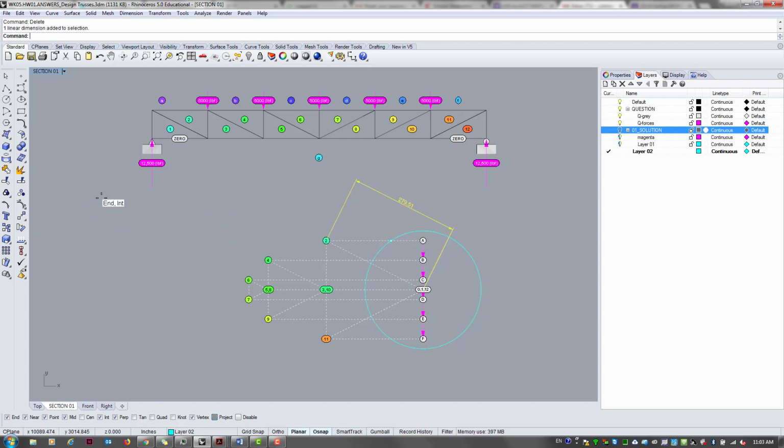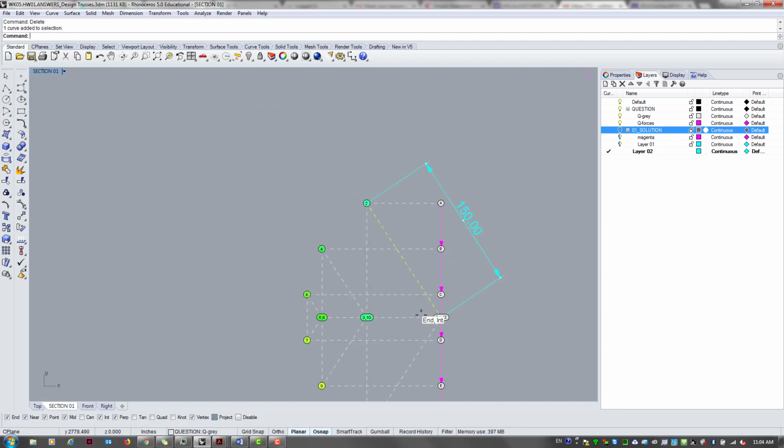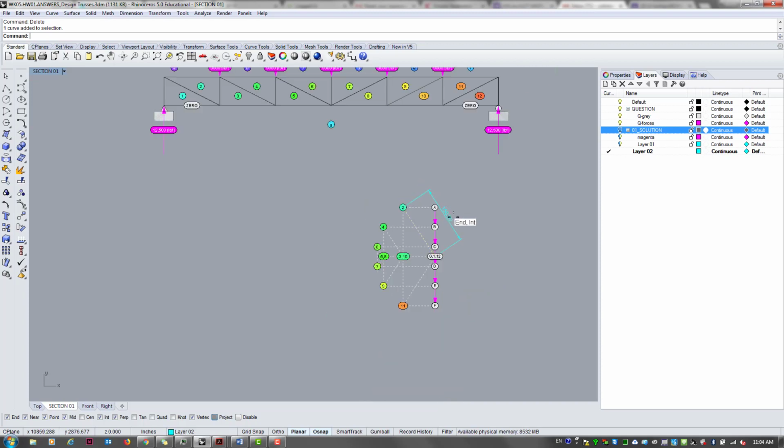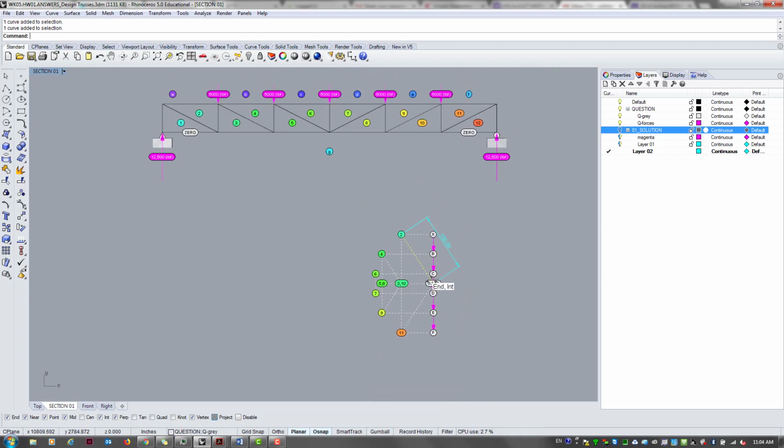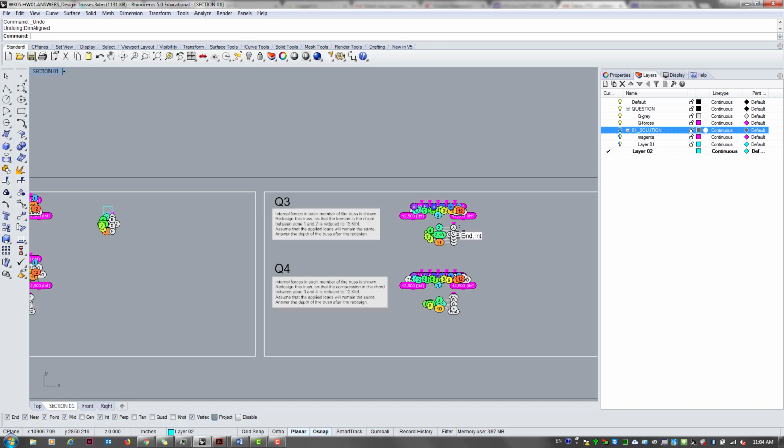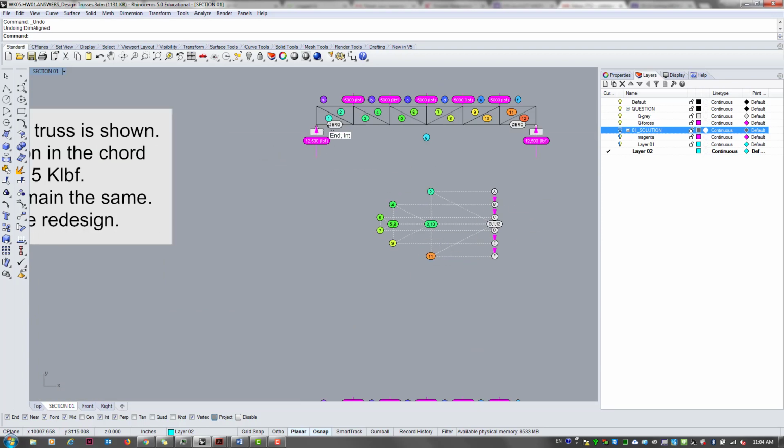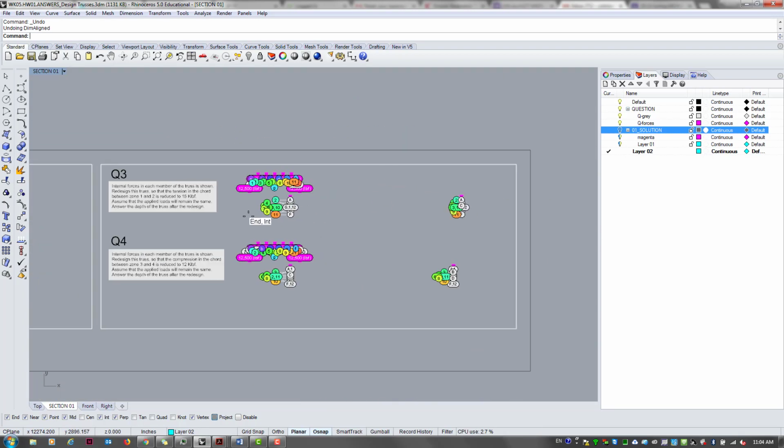And so I'm gonna turn the edit point on for this dimension. I'm gonna grab this whole thing and then scale 1D and grab the 2 and make sure that it snaps to that point. That way the resulting 1, 2 ends up being 150 inches. So this is, again, I'm gonna use that angle to guide the depth of the truss. So I guess that's the only slightly tricky part, but I think just the ability to tweak this and determine the geometry of the truss is pretty neat.